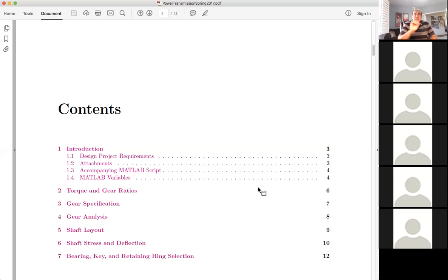So as I said, gears, shafts, and then the last part is the attachments. And these are the bearings, the keys, the retaining rings, and we have the formulas in the book, and we would want to make sure that the stress concentration factors introduced by the retaining rings or the set screws or by the keys do not actually lead to extra stresses that can lead to failure, even though we have assured that fatigue lifetime is, say, infinite lifetime.